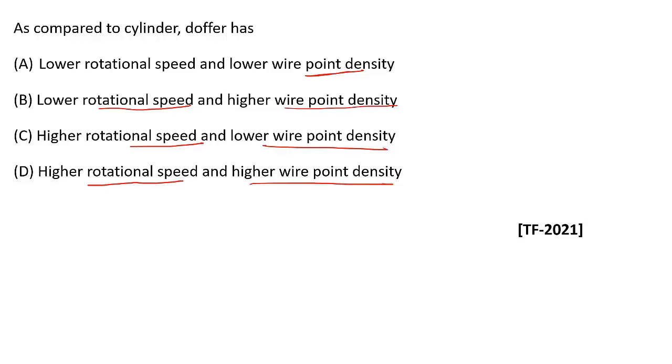So if you know about the rotational speed sequence in the carding machine, then the cylinder speed is highest, followed by licker-in, then comes the doffer. So the cylinder surface speed is higher than the corresponding speed of the doffer. This speed difference means that the web is condensed on the surface of the carding machine.